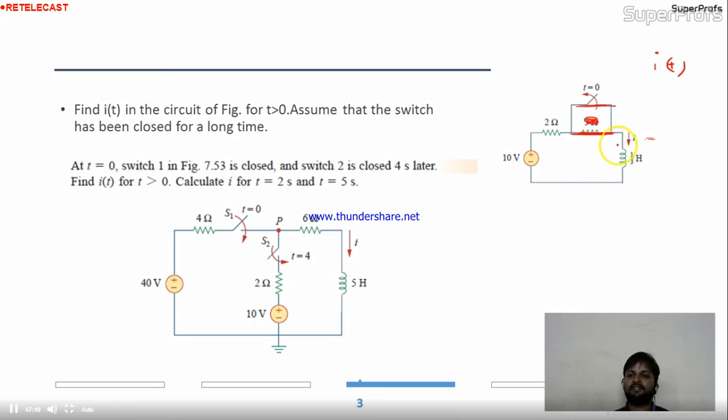So for the initial steady state, the inductor behaves like a short circuit. So your current I0 minus is 10 divided by 2, 5 ampere. Similarly, if you are having I0 minus, you are having I0 plus, and that is 5 ampere.